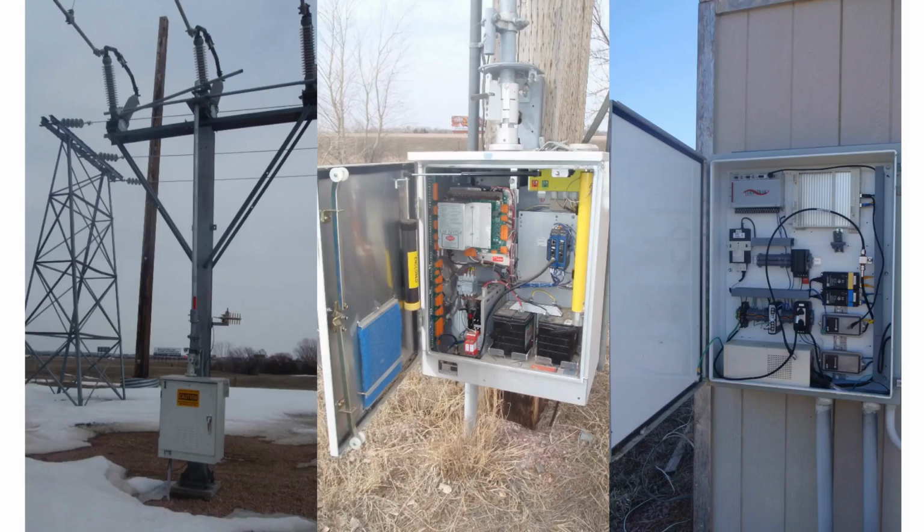2. Create a human-machine interface, or HMI, that presents all data and enables all commands necessary for a user to understand all relevant statuses and intuitively operate the system. And 3. Integrate two types of RTU to show basic input-output functions, or I/O, using Modbus with control from an HMI. These tasks required mapping network infrastructure and including safeguards in the HMI to account for different levels of user permissions.